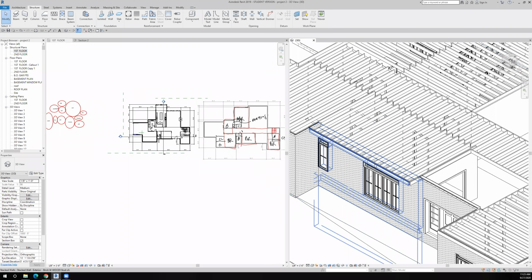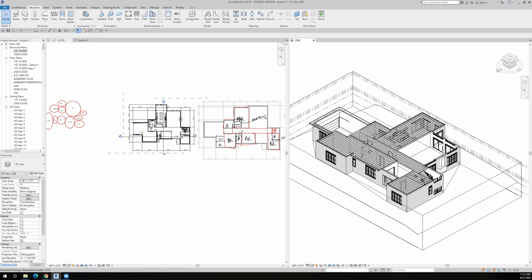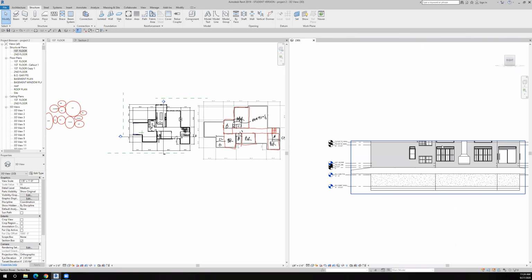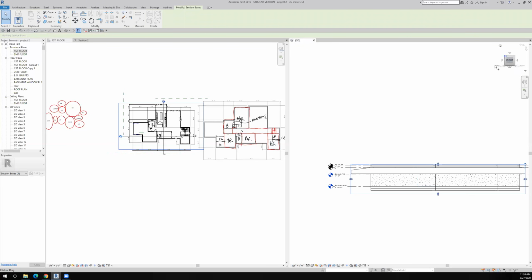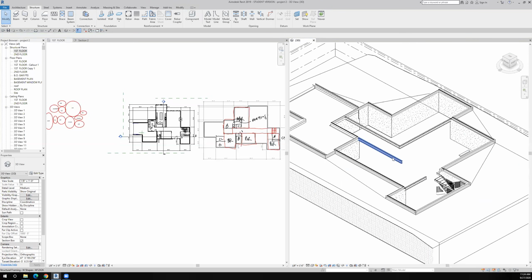It's time to put in the first floor joist framing now. We put the steel beams in the last tutorial, and I want to change what I'm looking at in terms of my 3D view. I'm going to come over to the front and take my section box and just drag it down so that it will show me between the basement and the first floor. So I think we can see the steel beams in there. Yes, we can see the steel beams that I put in there. They're in there, and now we need to put our framing in there.